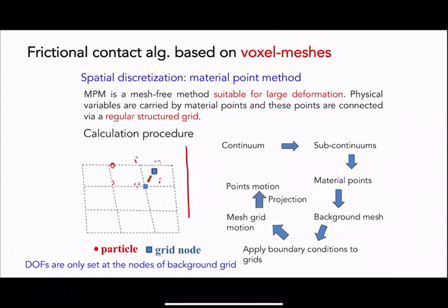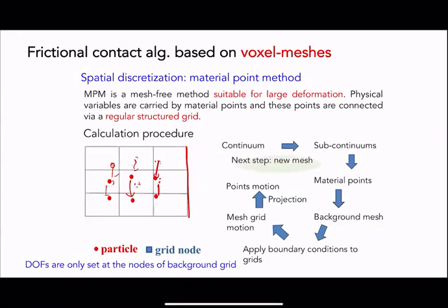So the material point would move according to the displacement, from the old material point to the new material point, and this movement allows us to carry the information into the evolved geometry. We then use a new mesh, and on the new mesh we update the level set to give us the new boundary, so that we can evolve the deformations without modifying anything on the mesh.